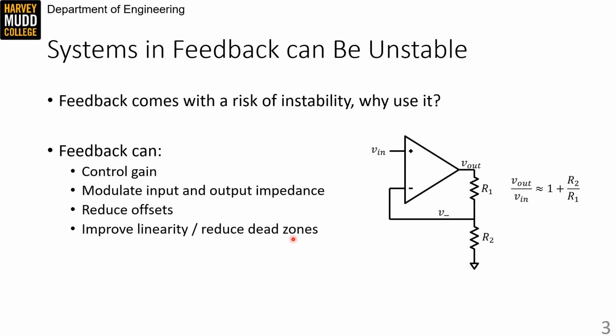And as a result, the dead zones appear much smaller on op-amps because the feedback forces the output signal to live outside of them. As a result, Class B amplifiers are often acceptable as the output stages of op-amps, even though you'd expect them to introduce lots and lots of distortion. Feedback reduces their effect.